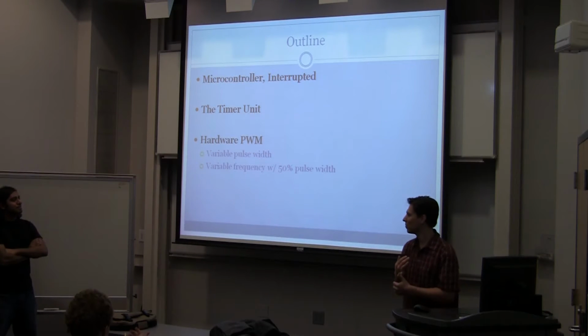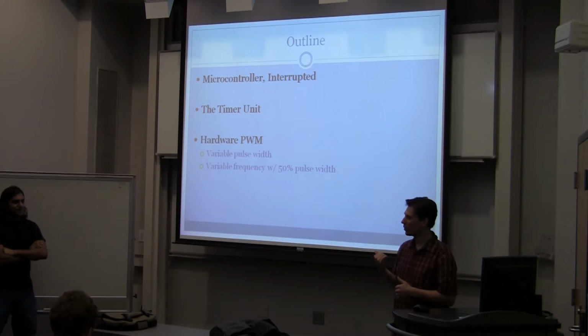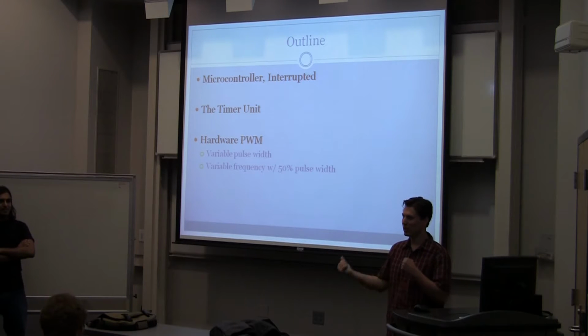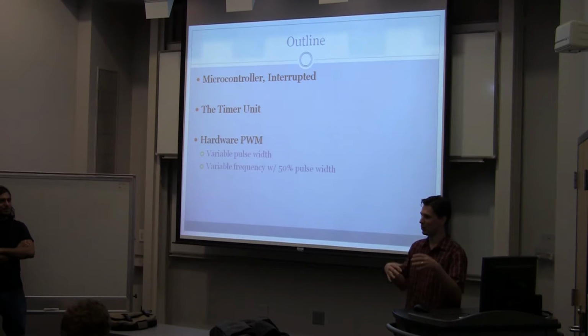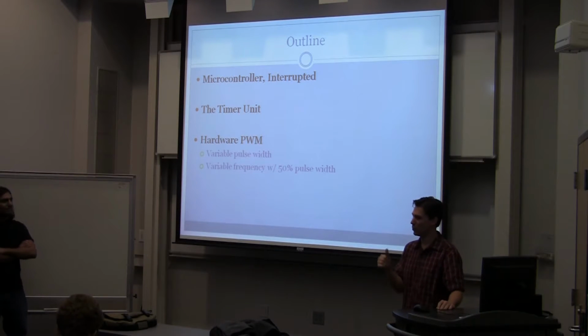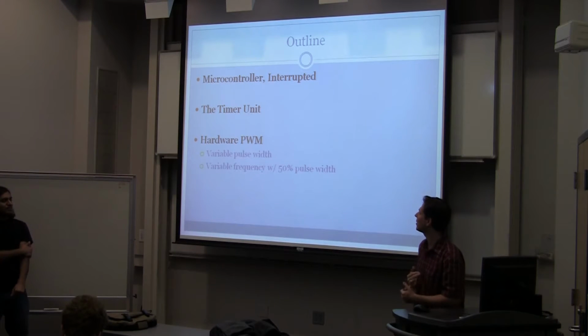All right, so now the main part of the lecture. We're going to talk about interrupts, which are really neat ways to get your microcontroller to do various tasks at a set frequency, for example, or to react to a button being pressed immediately without having to go in a loop and constantly check that button.